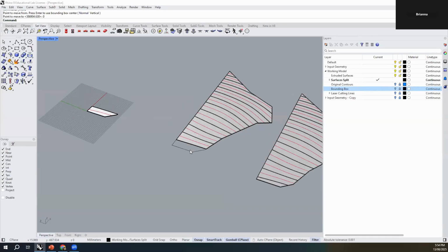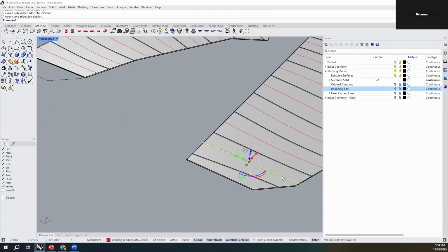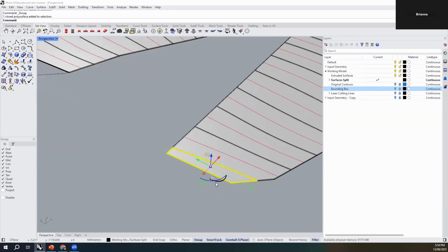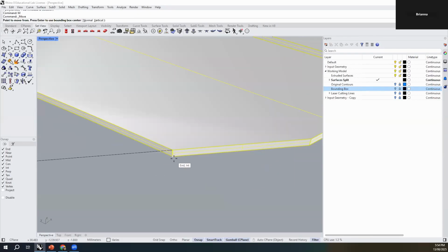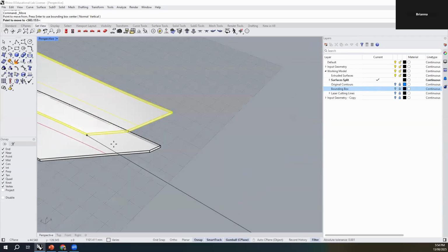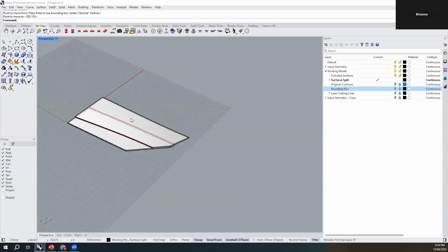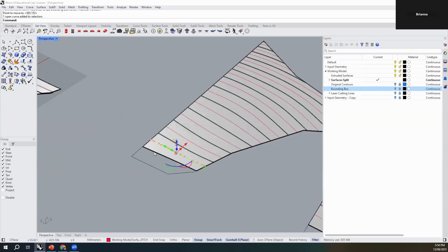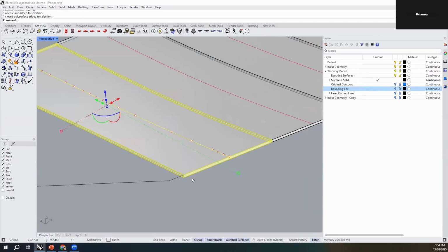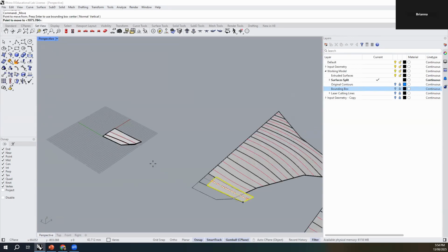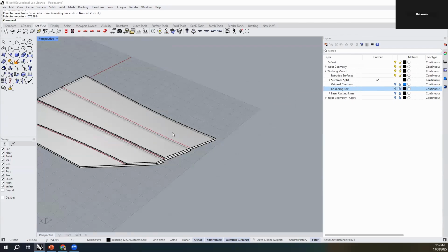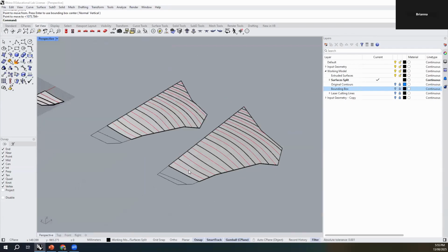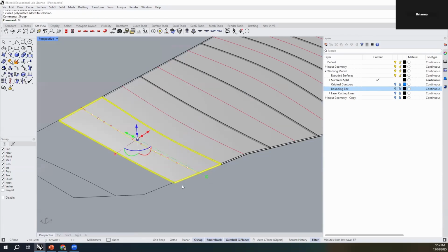So we're starting with this piece here, and then we're moving on to this piece. Oops, this piece here, for example. This piece, this component is actually redundant. We don't need it anymore. And what I would do is I'm selecting this front edge, and I'm aligning it to that edge. So when you get to laser cutting your model, you will be able to do exactly the same thing when you're assembling after it's been cut. You'll have those etch lines as a guide for you to then assemble your model, and that's really helpful in creating an accurate model.